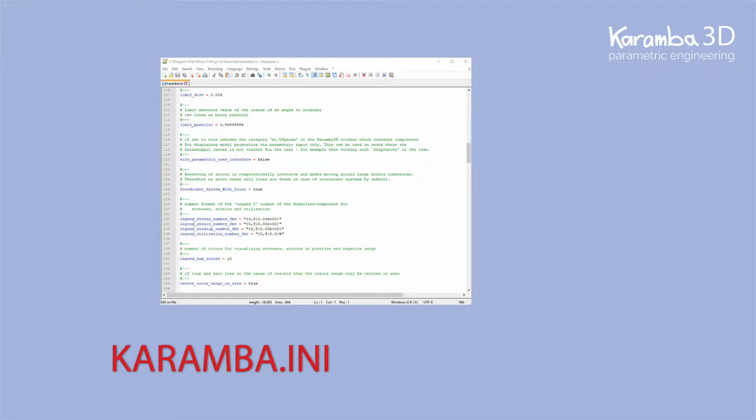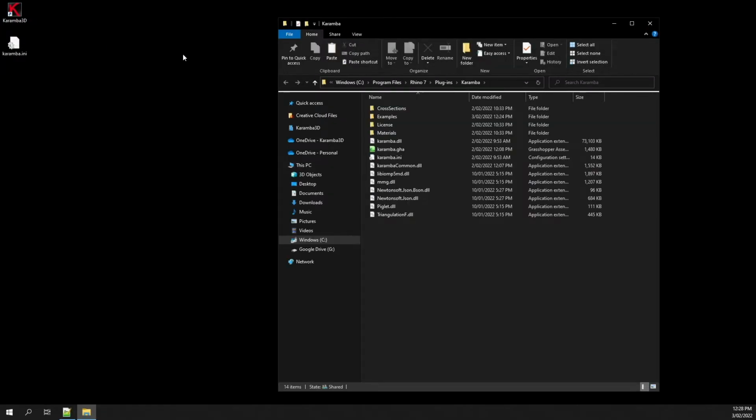Hi everyone, in this video I'll be showing you how you can use the Karamba.ini file to edit the default settings of your installation. This Karamba.ini file can be found in the Karamba folder of your installation. There is a shortcut if you use the standard program installation to locate this folder, and this is typically the plugins folder of your Karamba installation. Here you will find the Karamba.ini file.